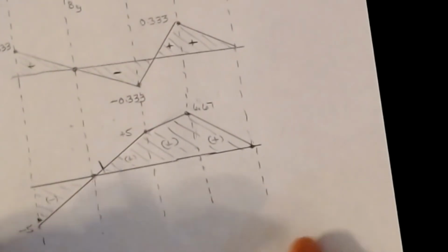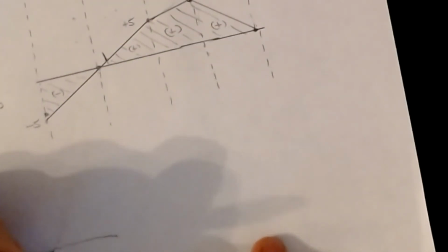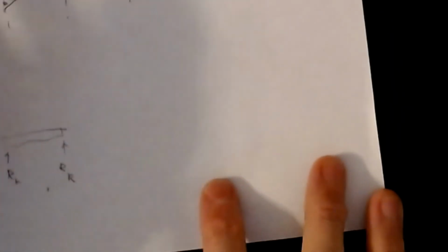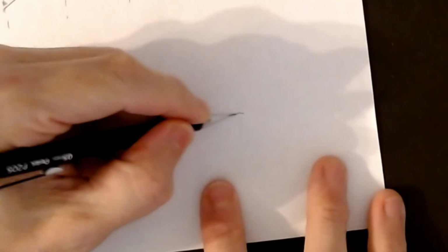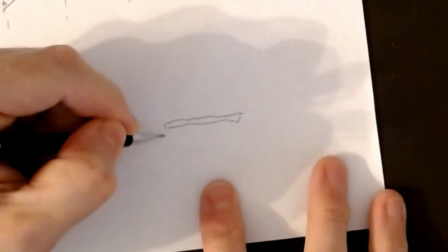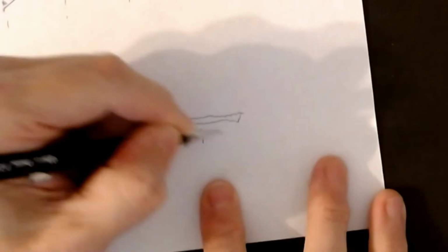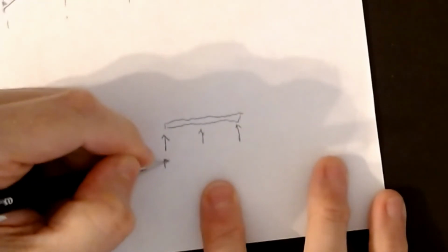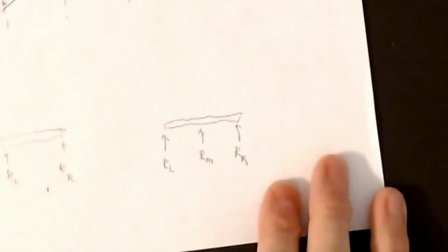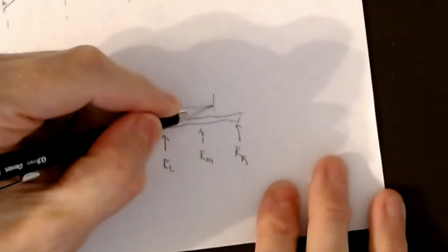Typically, we look at the panels as being some function of 2 point loads, where we have an RL or an RR. If I pull this up like that, you can also have more complex systems of panels, maybe an indeterminate panel where I have an RL and an RM and an RR, and it's the exact same game depending on what you have to do.